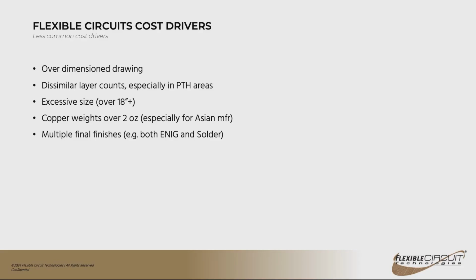And so you're basically getting rid of copper, which helps, and you're getting rid of some of the dielectric space in between the layers, and so you can get the same impedance without going quite so thick. So yes, that is a trick that's being used on a pretty regular basis.